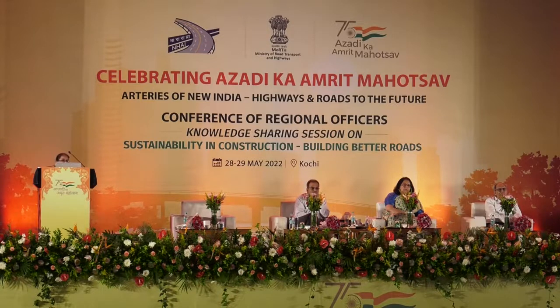So if you have to use this product, you are supposed to use it within 6 to 8 hours immediately, otherwise it will start settling, and then the contractors would have faced the issue of crumb rubber settling down in the bottom. So application wise, when we are talking about crumb rubber, 55 can be used in high traffic areas and 60 can be used in very high traffic areas.